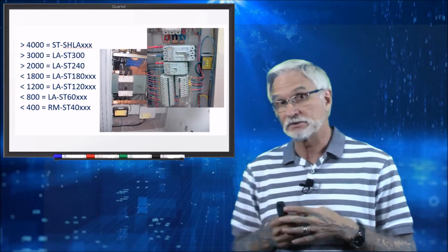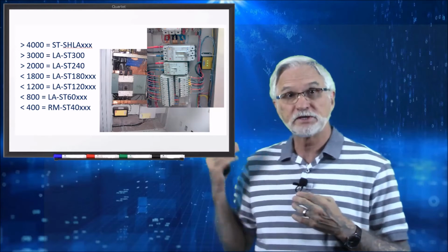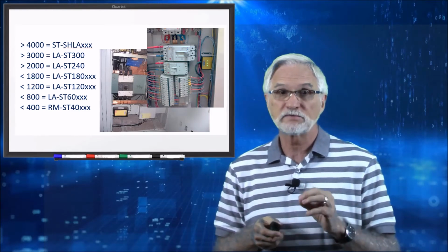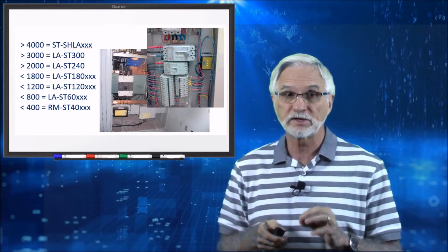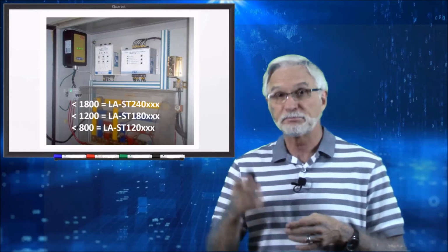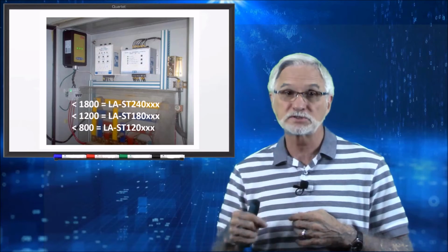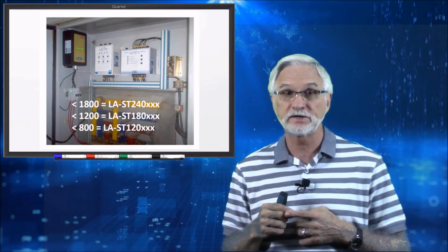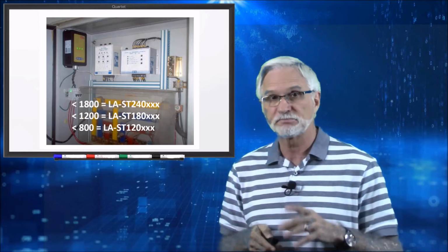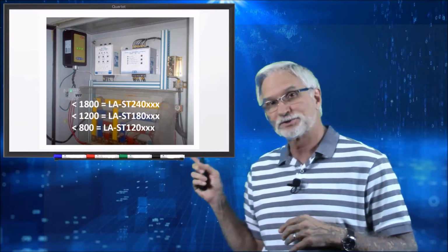Main distribution panels. We know all this, but here's your amperage and your voltage breakdown on the model numbers. So whatever that mains are, main circuit breaker rating, there's the typical units you would utilize. Automatic transfer switches, again, in parallel with the bus bars, typically on the load side of that generator automatic transfer switch, 1800 amps and down. It's very well recognized there. Notice the nice twisted cables or braided cables on the unit itself there.